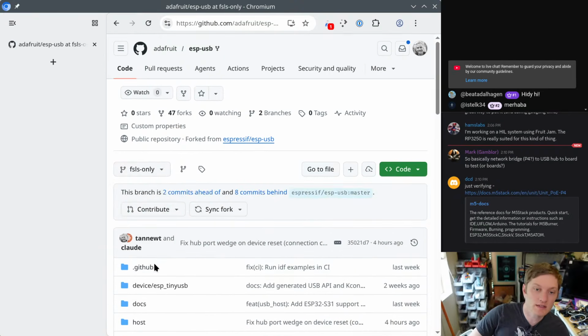One thing I ran into is that the P4 host code doesn't support full-speed devices behind a high-speed hub. It is a high-speed controller on the P4, but if you put another CircuitPython device on the other side of a high-speed hub, the thing talking to the hub has to do all this split transaction stuff for carrying full-speed transactions over a high-speed link, and that's kind of a pain.